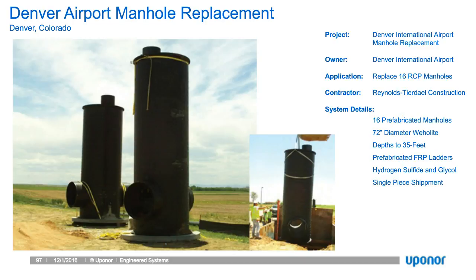As you can see, we have a top riser that extends. On top of these structures would be a cast-in-place rebar reinforced load relief slab to mitigate the high wheel loads of the aircraft and distribute those loads to the soil. And that's something we can do on any project to accommodate the vehicular or aircraft loading with a load relief slab above the structure, standard design practice.